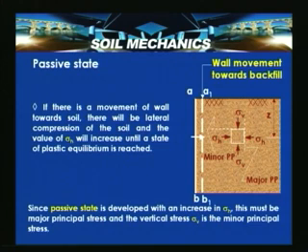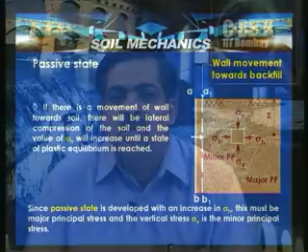But in both active and passive states, at a particular depth, the vertical stress remains constant because the weight of the soil involved in the process is the same. So, at a particular depth z, the weight of the soil involved in the active and passive states being the same, sigma v remains the same. The only changes occur in the lateral stresses, that is, horizontal stresses sigma h. In one case, when the wall moves away from the fill, there is a decrease in sigma h. When the wall moves towards the fill, there is an increase in sigma h.